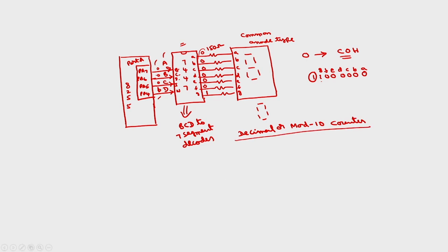Here basically you have to give only 4 bit BCD. So, you assume the same locations, move AX comma 5000, move DX comma AX, then these connections are, we are assuming only we have to give output the BCD. Here also you have to program all ports as output ports in mode 0. So, OUT FFH comma AL. These two instructions will program all the ports as output ports in mode 0.